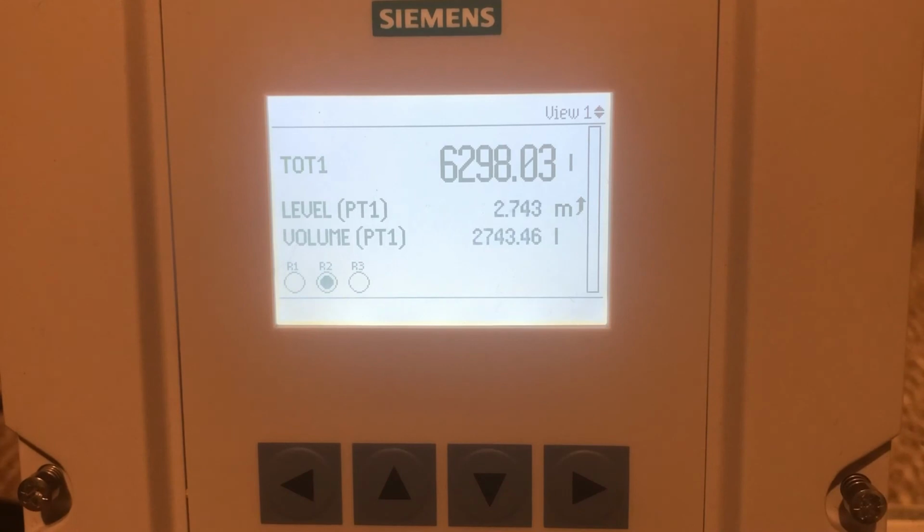And now I also have an external totalizer, so I can display the total value, and I can also externally totalize. So as you can see, pump number 2 is turned on first because we're doing alternate duty assist. And pump number 1 will follow shortly. And we can see that relay 3 has also been configured now. And as soon as I lower my level back down below 0.5 meters, my pumps will turn off, and then I will totalize, and I can hear the relays. So now I've totalized again, and I've done my external totalization.